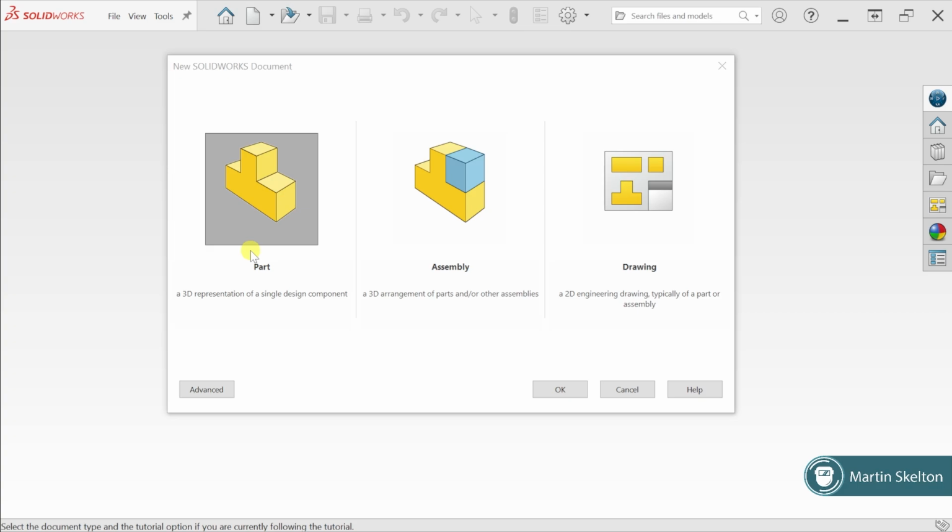Now the interesting thing about SolidWorks is if I generate a part file and make it into my assembly and then generate a drawing or a manufacturing drawing from my assembly file, if I decide to change something in my part file, it will change in my assembly file and change in my drawing file. So the beauty of SolidWorks is that the three file types are interconnected. If you modify one, it will follow to the next file type. That becomes very, very handy if you have just simple changes, even fairly major changes, it can still filter through.